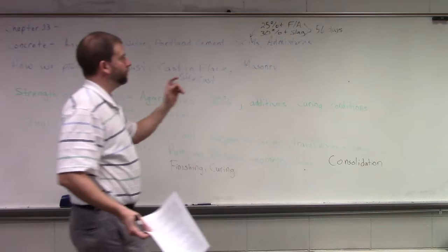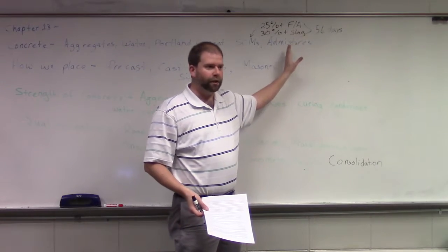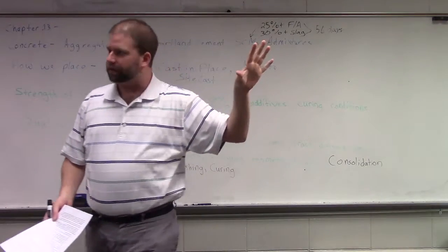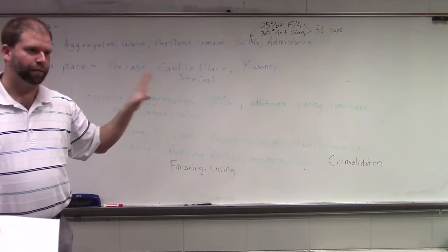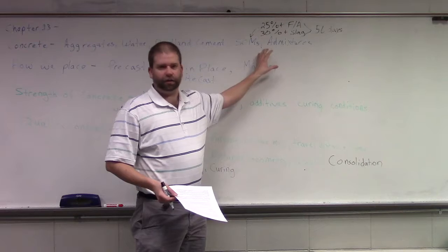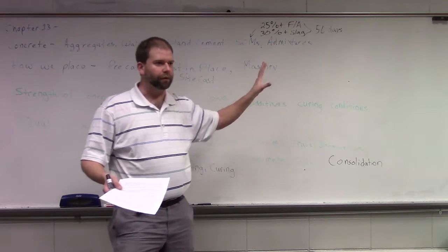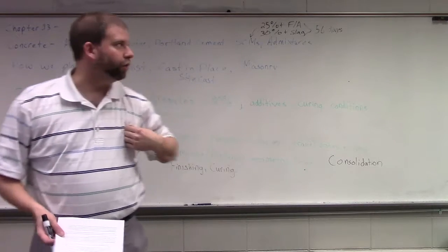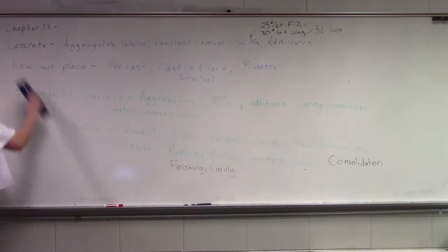But be aware that the ready mix plant, the lab, they've done extensive testing. Okay, so there's all kinds of ways that you can monitor this in the field. We can drop temperature sensors into the concrete. There's a lot of ways where we can keep track of this. We can know something within the first 2 or 3 days if it's trending properly. By the 7-day test, we should know if there's going to be major cause for concern. So, okay, that covers that kind of stuff.